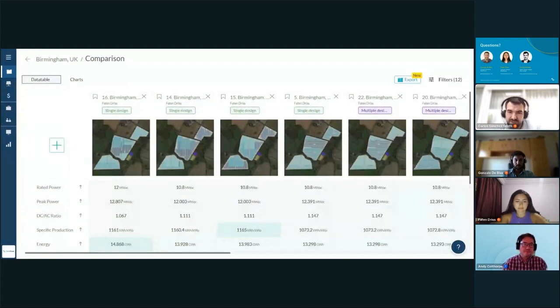But an interesting concept is that if you're using bifacial panels, the higher the ground clearance, the minimum clearance that we've been mentioning before, the more energy the system produces. So if you introduce all these concepts together, you'll have increased bifacial production, and your levelized cost of energy impact will be lower by raising the panels much higher. So I think that the effect of raising the bifacial panels higher can balance the extra cost of the structures. And in some cases, if you directly compare a 2P tracker with a 1P tracker agrivoltaic, the agrivoltaics would be more expensive, but in some cases it would be a yes or a no-go to that land. So in my opinion, yes, it's justified.